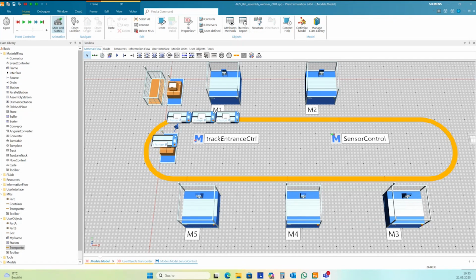Yeah, so I see Amir just put a question there. I guess I can read it. Is it possible to use the Plant Simulation Python interface to develop custom methods for tasks such as sensor control? Yes, you can access all the SimTalk methods you have, but it's really slow, and so you need to check if this slows down your simulation.